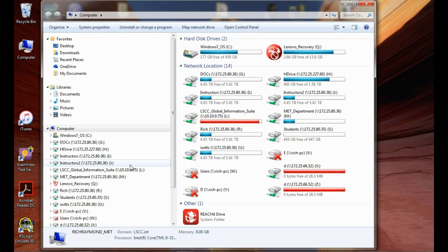right? So if I've got 15 volts on this side of my regulator at 1 amp, and I've got 5 volts on this side at 1 amp, then my regulator is dropping 10 volts. 10 volts at 1 amp would be 10 watts that the regulator would have to dissipate. If it couldn't dissipate that, or if you tried to get 20 amps out of it, what's going to happen? It's going to burn up, right? So those would be the considerations we would have.